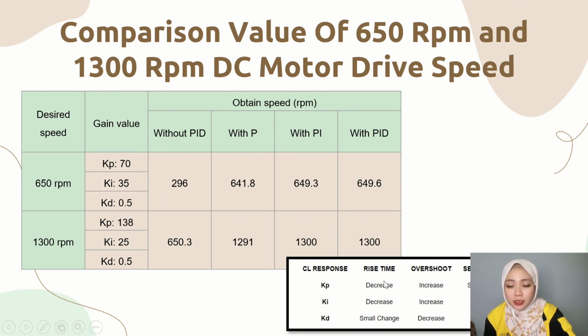So this is the conclusion of the controller response, covering the rise time, overshoot, settling time, and steady state error for each gain, which is proportional, integral, and derivative. That's all from me.